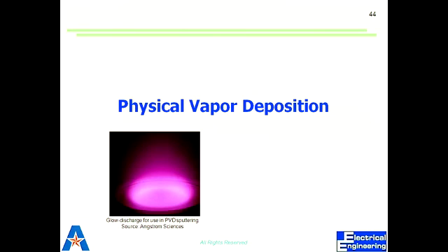You can do liquid deposition also. In that case you have a liquid you want to deposit, you use a chuck like a photoresist chuck, deposit it, let it rotate, and it gives you a film. That's also a physical deposition, but we call it something else. It's not PVD or CVD.